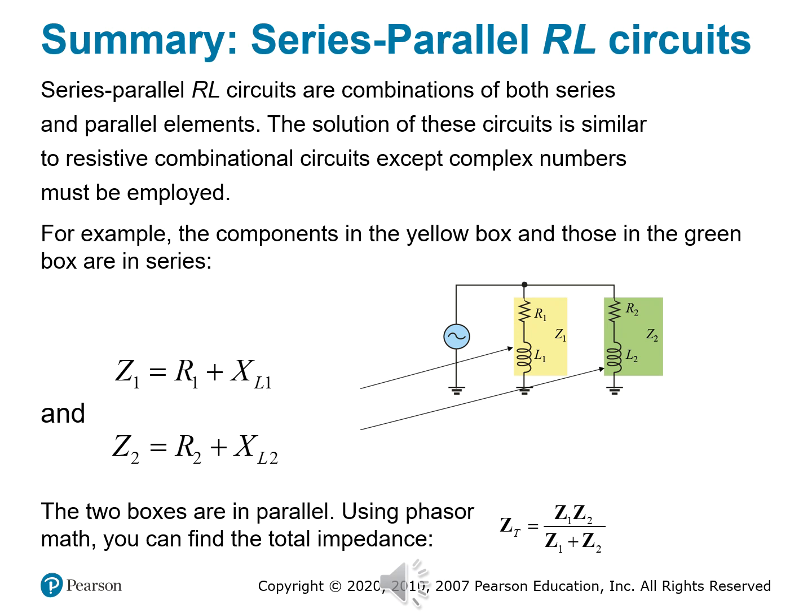So think about this. Filter sections, amplifier networks, and switching power supplies. These are just some of the places you'll see this in real world applications. Other things could be RF tuning circuits with multiple branches. Again, this helps you understand how to combine RL branches in mixed configurations to allow you to control impedance across frequency, tune time delays, or balance energy delivery and noise filtering.